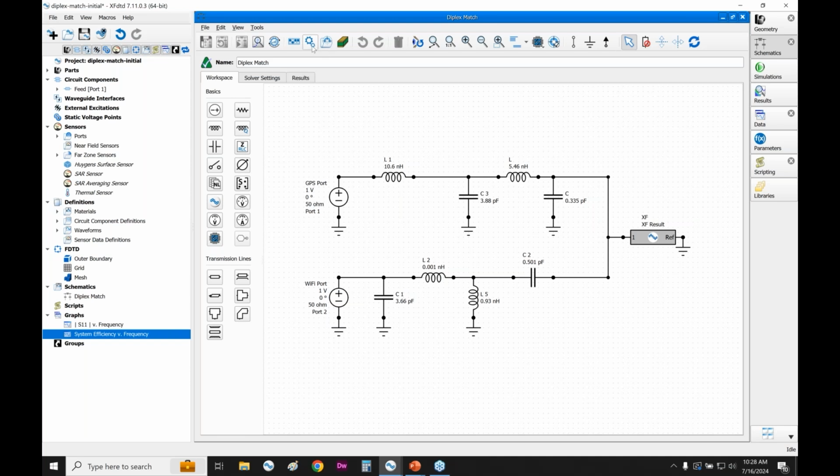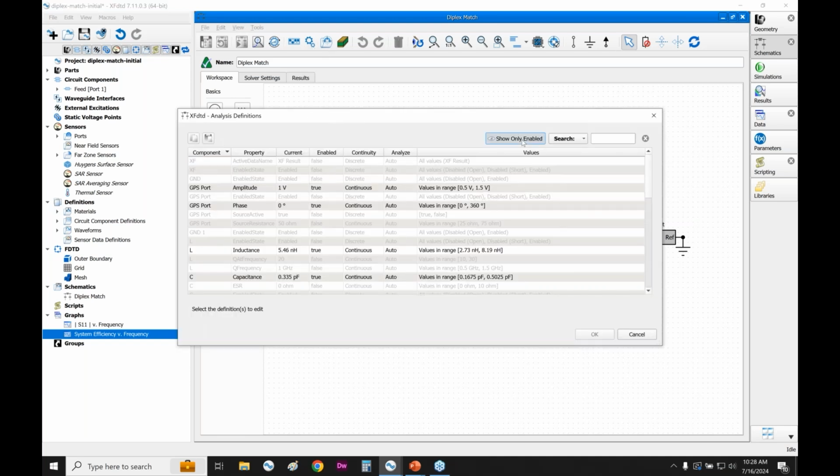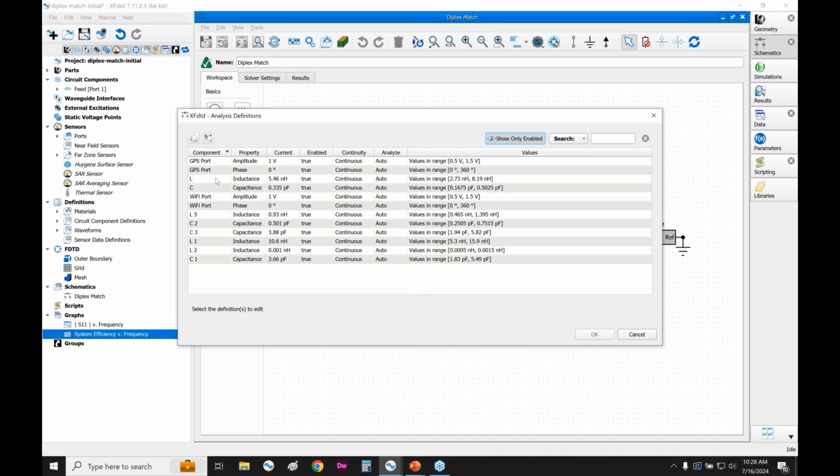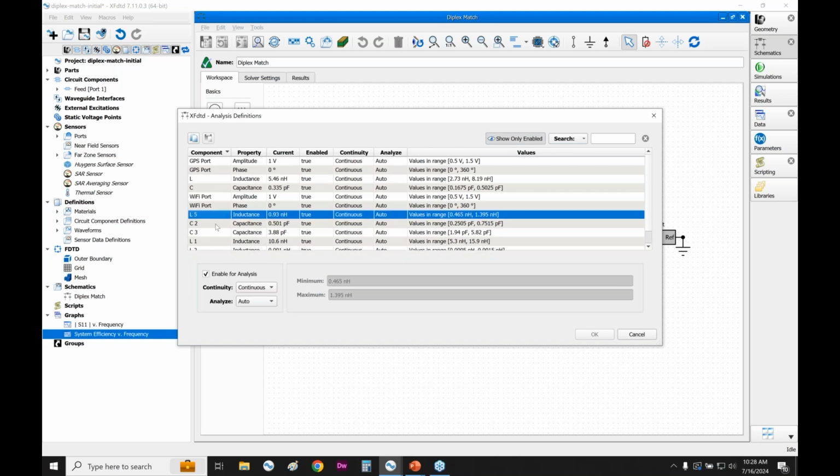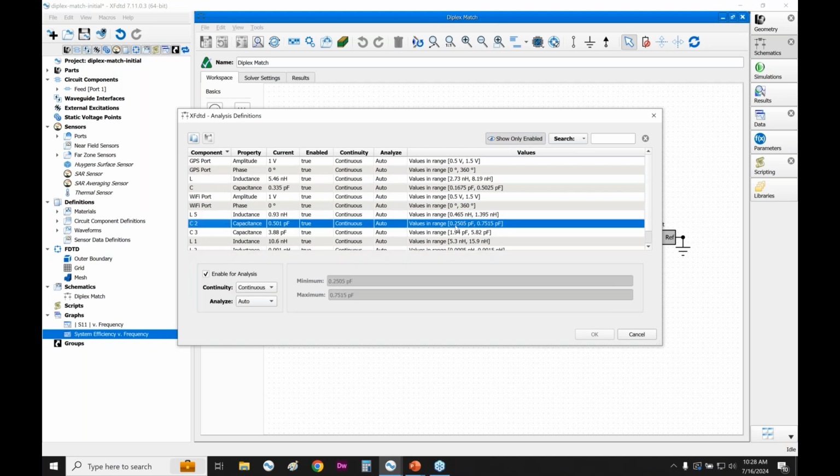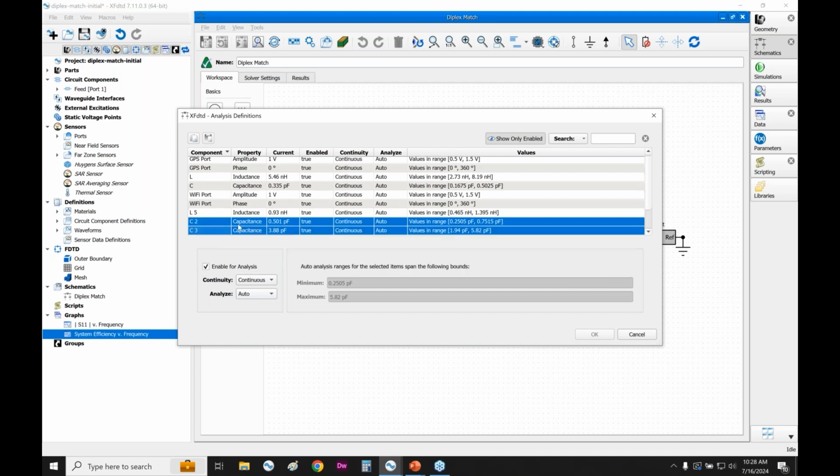So similarly, here we have our table that allows us to select our different inductors and capacitors and specify the range that those values can take on. If you're going to run optimization, you have to say, well, what is the range of component values that each of my components can take on? And so we can do all of that here through this editor, and remembering that there's multi-select available to make this easier to select multiple things at once.